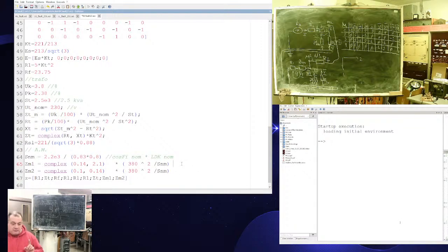First, I will do one moment. To show a clear effect without the asynchronous machine, I will multiply it by 10,000. It's just like switching the machine off. I'm simulating the action of the switch just by making the resistance huge, so it will have no importance.